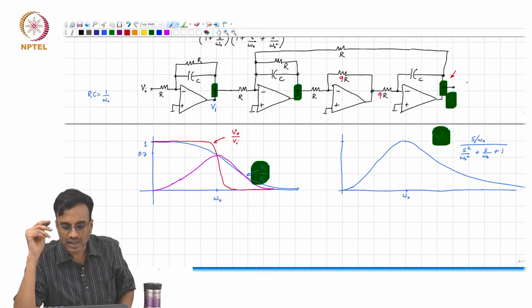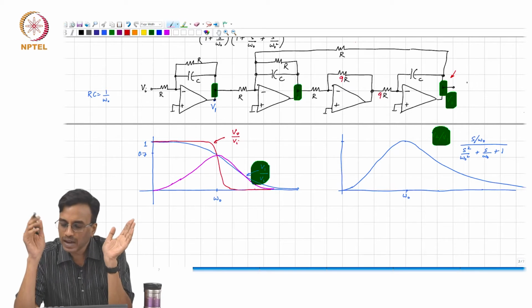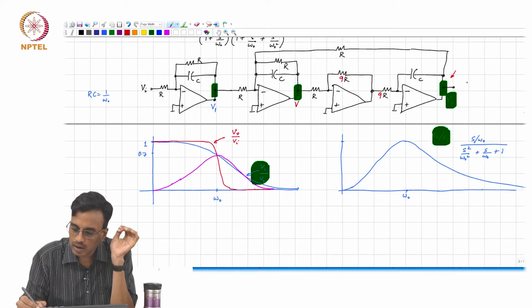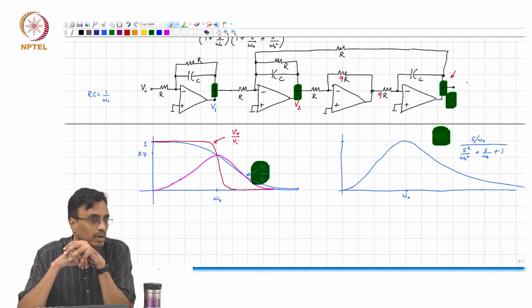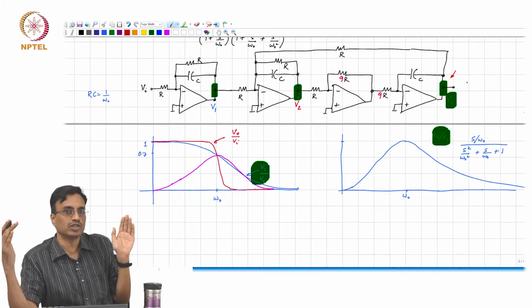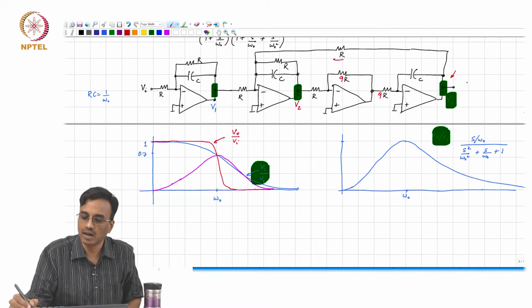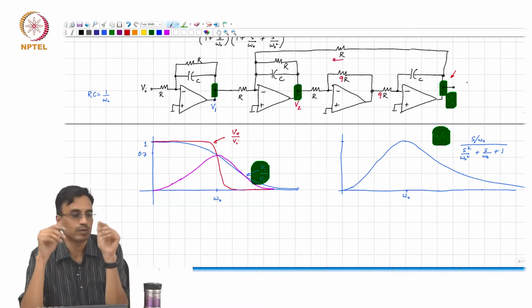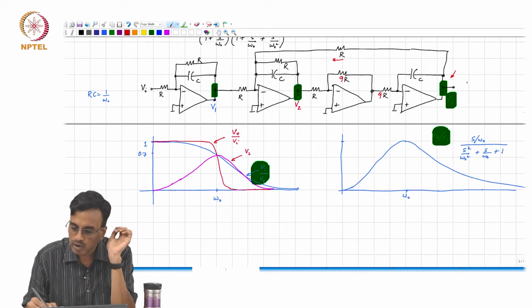What comment can we make about the transfer function from Vi to V1? It remains the same. What comment can you make about the transfer function from Vi to V2? Is it the same? Why? Because what's coming to that branch is not changing. The input output transfer function we know is not changed. So as far as V2 is concerned, the same current comes to that branch, so the transfer function at V2 has also not changed, right? So this is nothing but V2 over Vi.